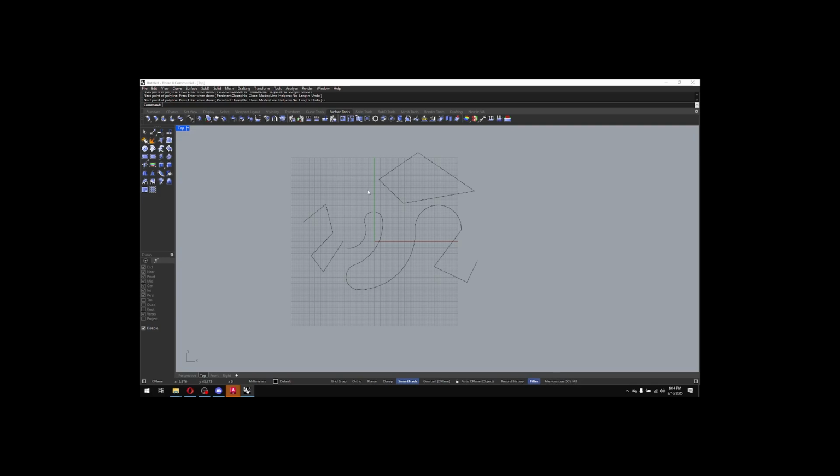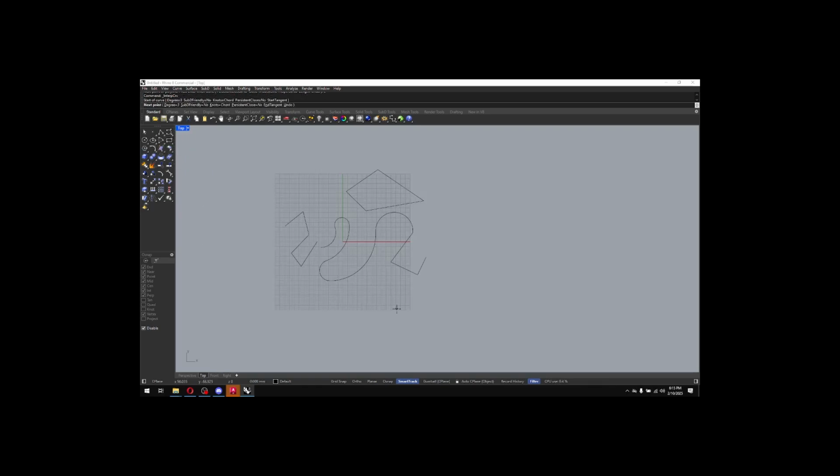Other drawing tools of importance over here that are 2D, again, all kind of work very similar to CAD. This one, I actually will hold down the left mouse button and click the second one. This is called Curve Interpolate Points. You don't need to remember the name, doesn't matter. The point is that if I click on this one, I get a spline that's going to stay within those points.